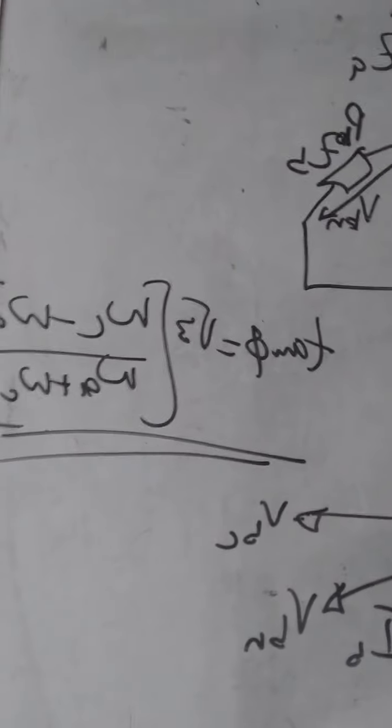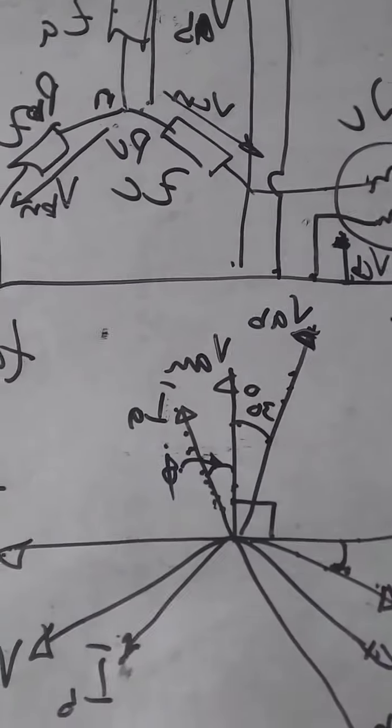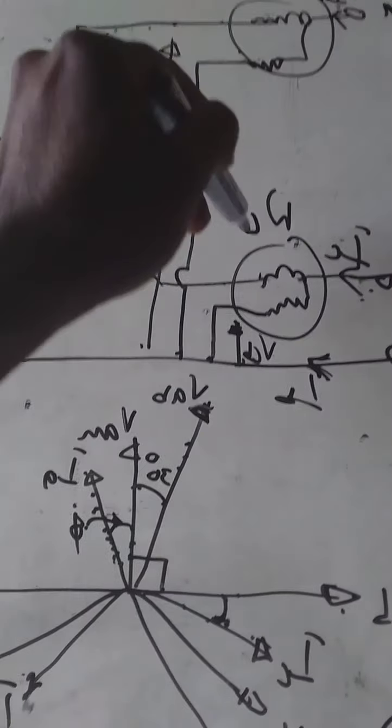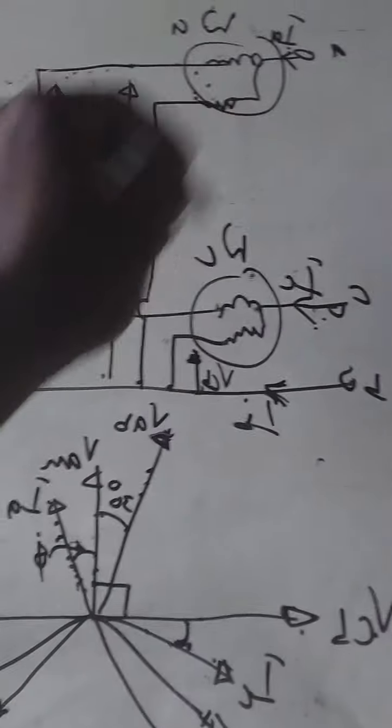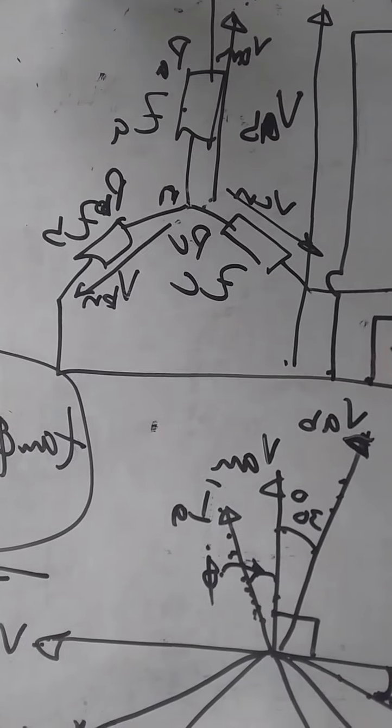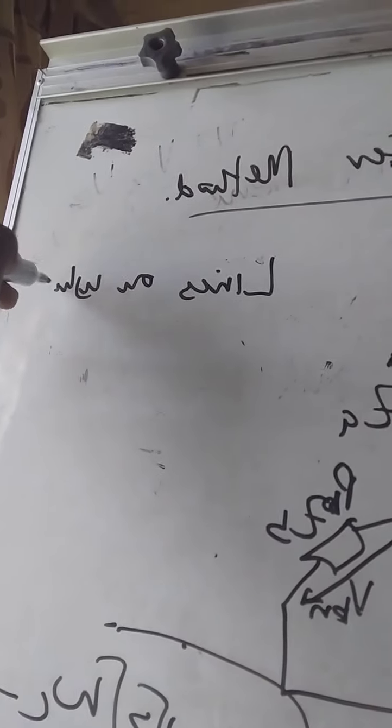And for this also we have different formulas. What will help you to determine this will be informed by two things. It will be informed by which lines you put the wattmeters on. If the wattmeters are placed on A and B, the equation will be different. If it is put on C and B, it will be different. So what will help you determine which formula you use to obtain the power factor will be, number one, the lines on which the wattmeters are placed.